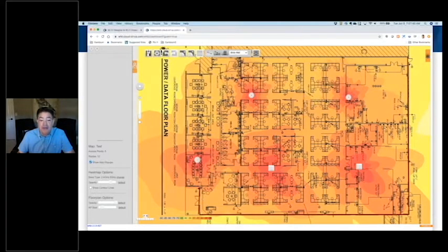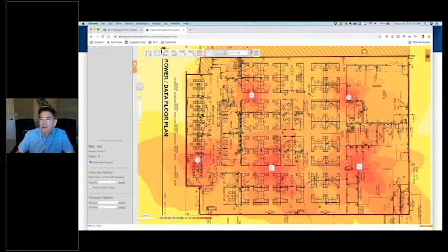The attenuation outside of the building is cut because I have this brick wall in place. And so I'm just going to trace the outside of the area, running into my thing there and there. So now I've outlined the building, and now you can see the RF is actually scrunched in a bit. I could maybe put 2 walls there if I think that the attenuation isn't quite significant enough for the type of building structure that I have.